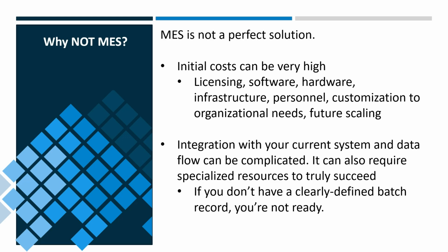And integration with your current system and data flow can be kind of complicated, and it definitely requires specialized resources if you want to actually succeed in your installation. If you don't have a clearly defined batch record already, then you're not ready for an MES, and you have a few steps to take before you can get started in implementing one.